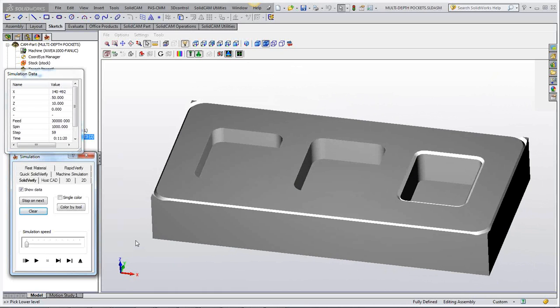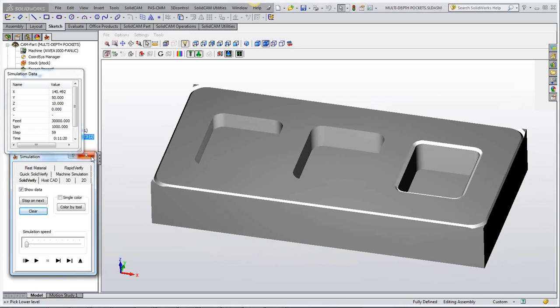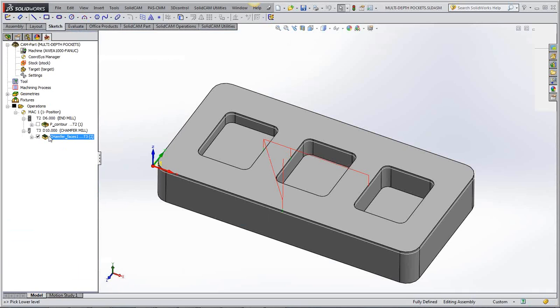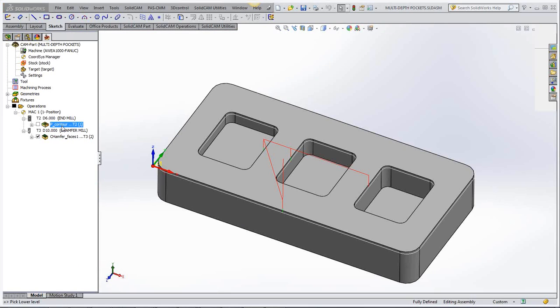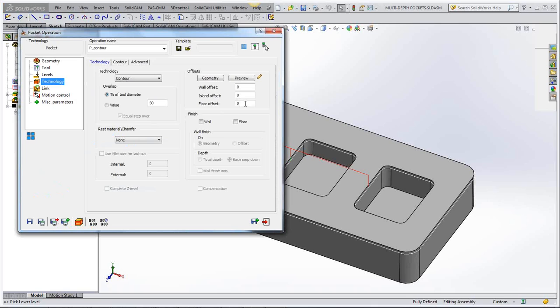Now then, here's a thing for you. Obviously I've retoleranced them geometries, and the chamfer is working on the original geometry, so this is where you find out things like that. I'd forgotten about that. I'd have had to have done my previous operation on the original geometry, so there's a little cock up for you there, live on air.